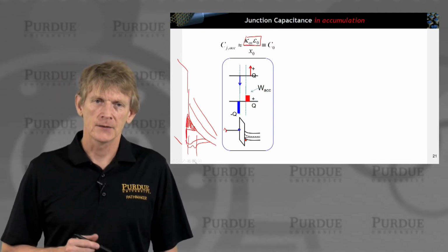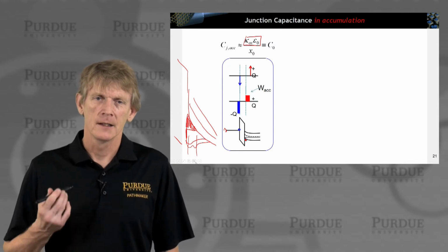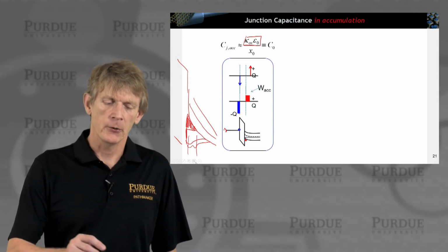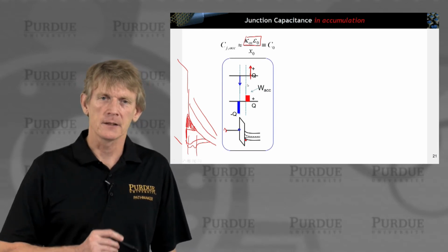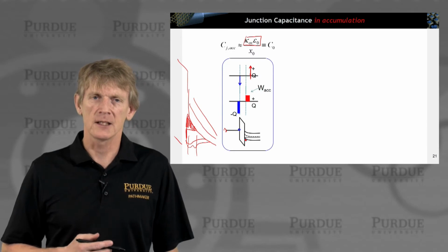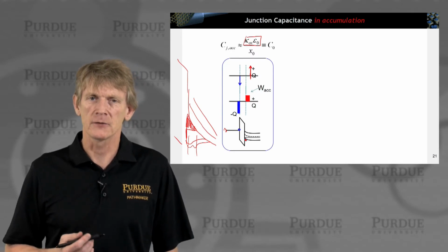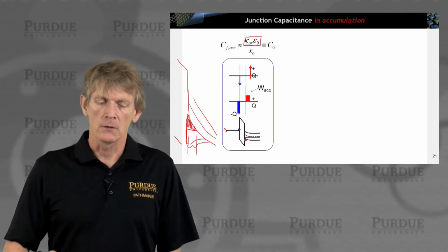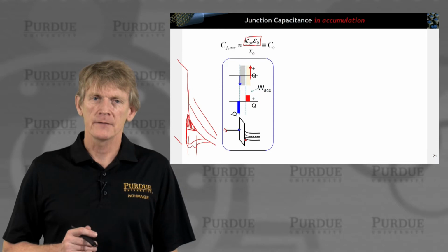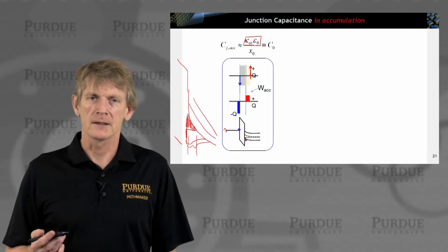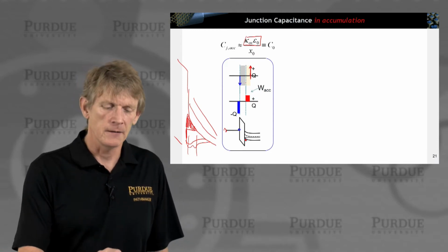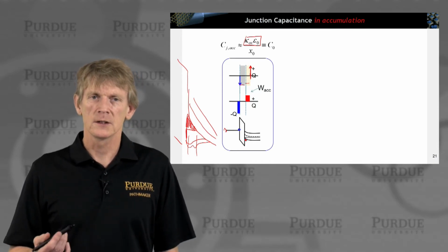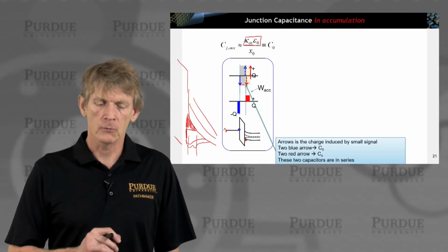So it is clear that the charge is not directly sitting on the interface, and you can account for it by treating it still like a delta function, so to speak, but this delta function is separated from the interface by some effective distance. If you have charges separated like this, in a series capacitor with different dielectric constants, you can model that with two series capacitors, like what we had done before.